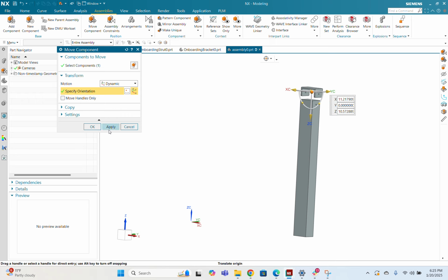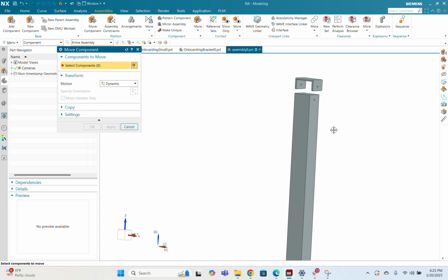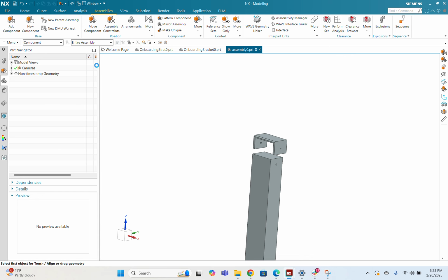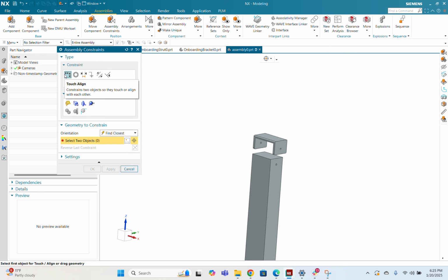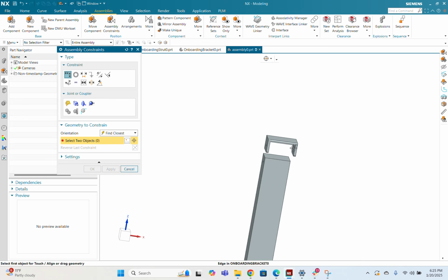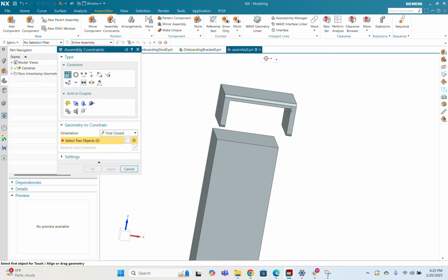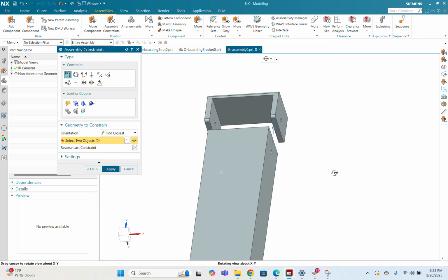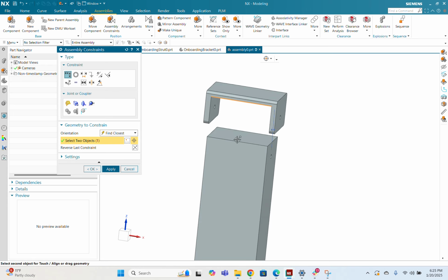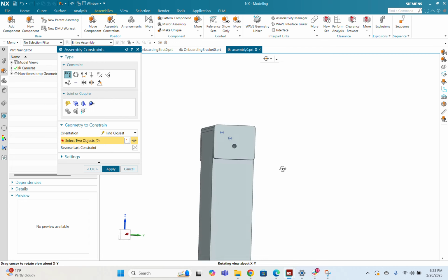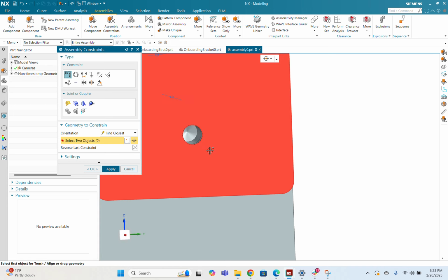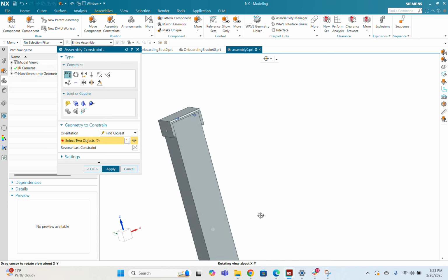And then similarly to constraints for a sketch, there's also an assembly constraints option. So if I actually wanted to make these touch, I would pick this one that's called Touch Align, and you can just pick this face, and this, and there you go. You'll see it fits right on there, and even the holes are aligned. So that's basically how you would apply those two things together.